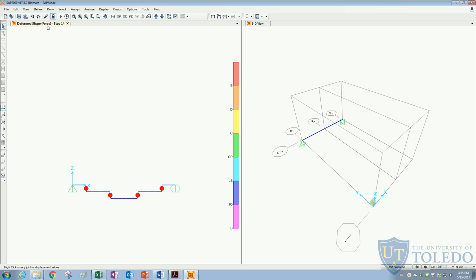So we can see that at the force-based analysis, these hinges fail pretty early on the analysis and pretty suddenly. And we also see that all the hinges fail together, even though these hinges close to the center, as I mentioned before, have both high shear and high moment, and these close to the supports have only high shear. The reason for that is that SAP2000 does not consider the coupled effects of shear and moment. So as far as SAP2000 knows, this hinge and this hinge have the same shear force on them, and the moment on this section here doesn't change anything for this shear hinge.